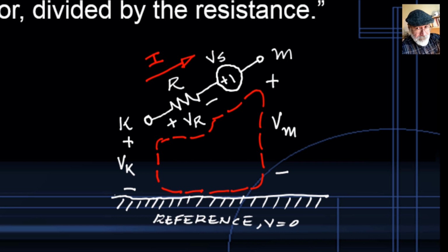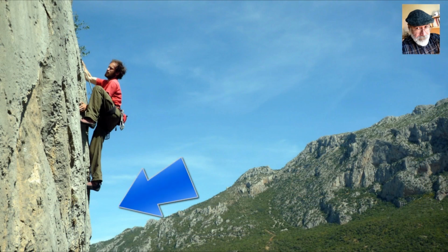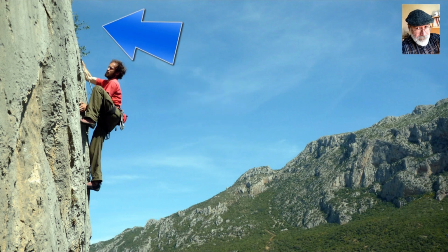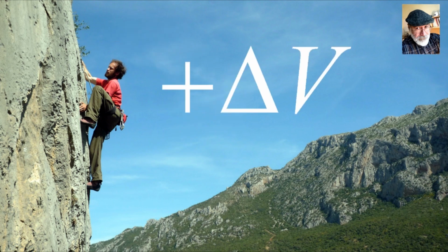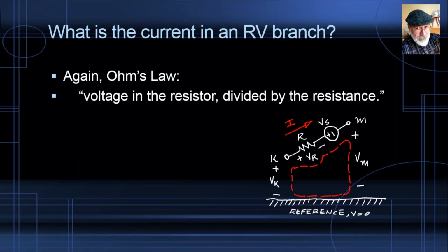By the way, when I write a KVL, when I climb up, when I go from a lower point in the circuit to a higher one in volts, I add the height, I add the volts. When I climb down, when I lose electric height, when I lose volts, I subtract. Just explaining why this equation is like that.